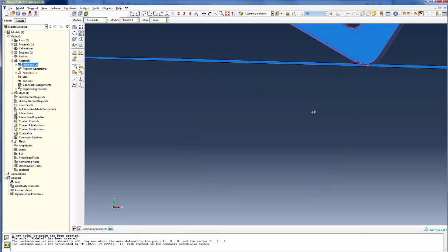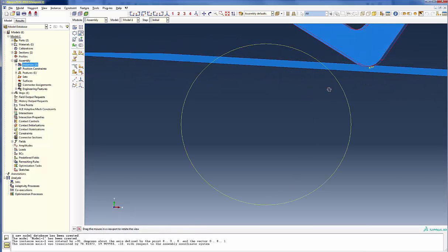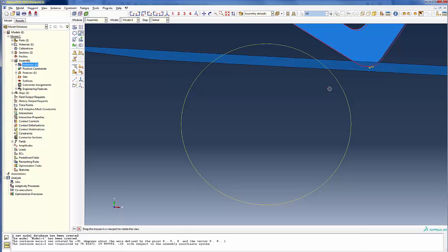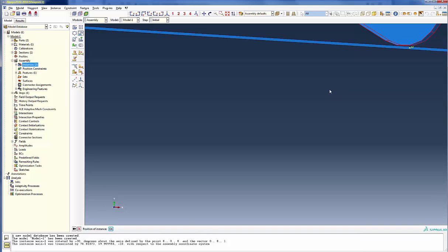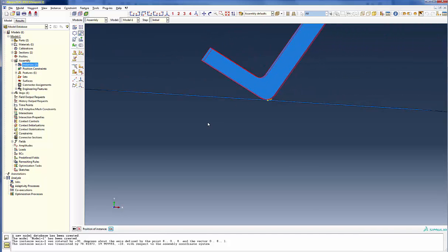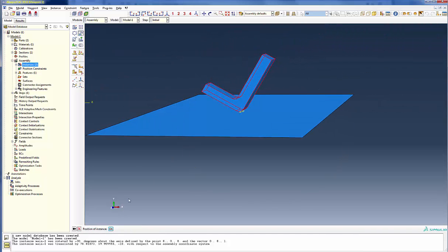Now, if you're not 100% sure, go ahead, give it a more reasonable dimension, such as in this case, I'm going to give it 1/4 millimeters, so 0.25, and say enter, just to be completely sure that you are right above the plate and there's no possibility of any kind of interference, as you see from this drawing. Okay, so now that the part is oriented, you say OK,